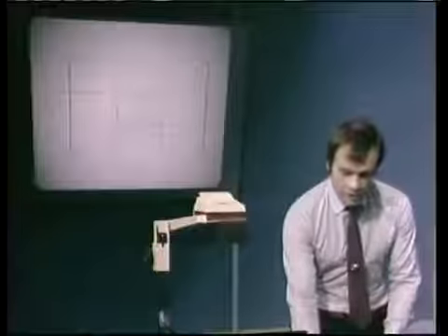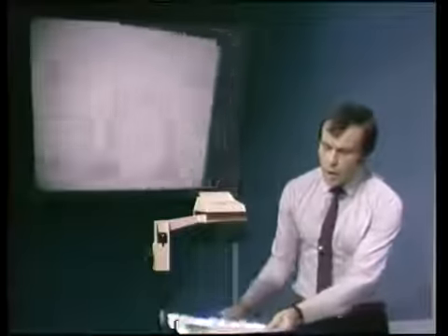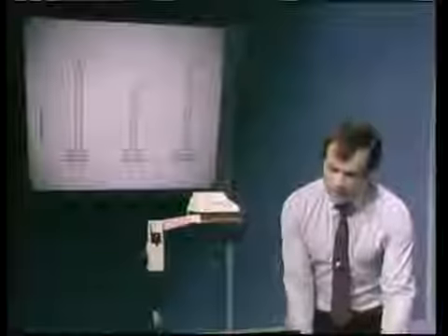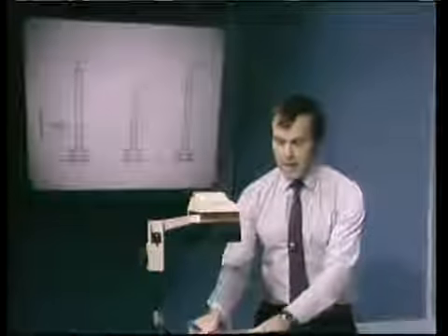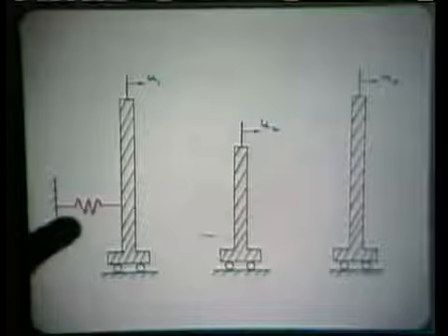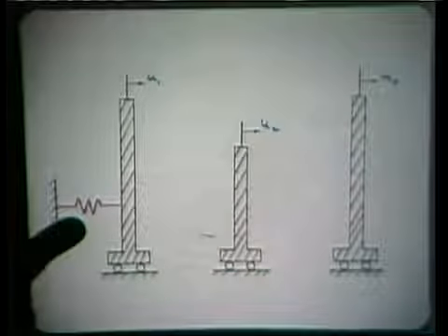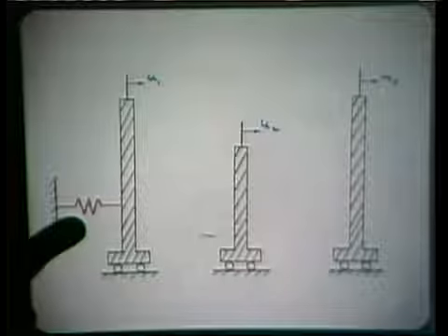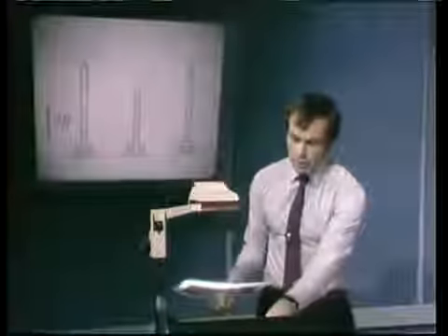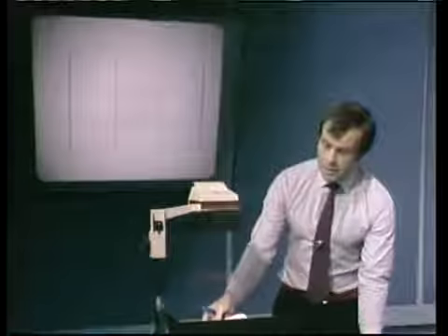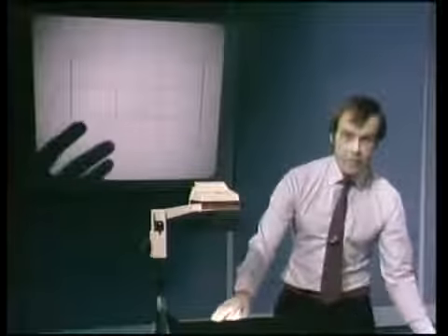The process then is the following. We are using this cart system and we're adding one spring on. That is the first addition, spring k1. Mathematically, this means that we are taking our K matrix with blanks everywhere, and we are adding into it this one element, k1.